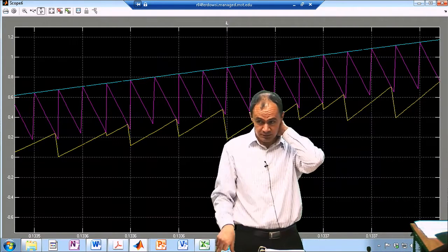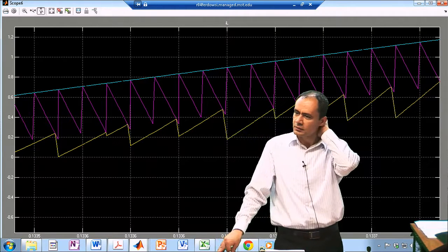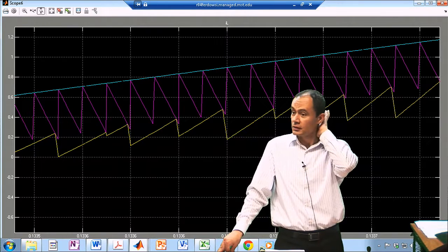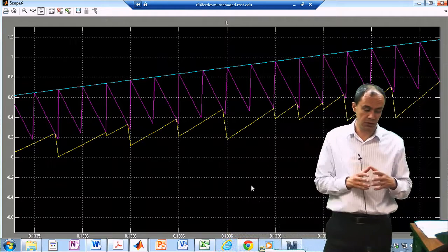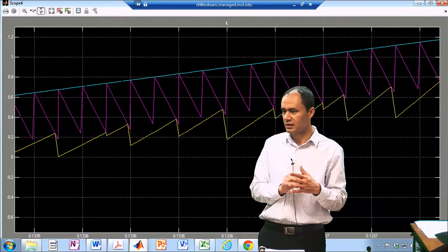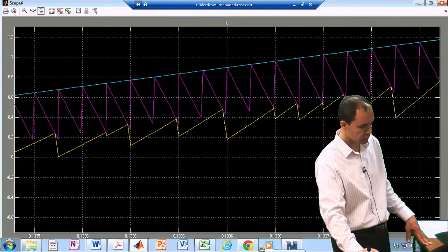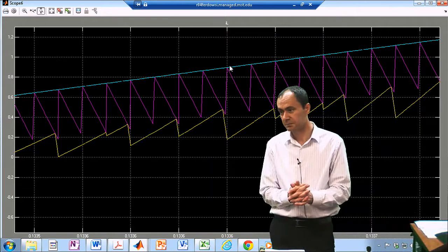Question? Is this PCM applied to a rectifier? Is the peak current mode control being applied to a rectifier because the output is a rectifier? Yes, exactly. Actually, we are using a peak current mode controller to force the inductor current, which is this yellow trace, to follow the reference, which is this blue one, with the existence of the external ramp.